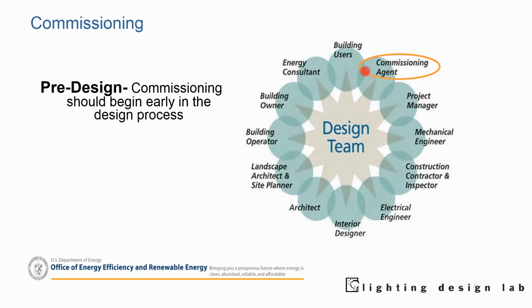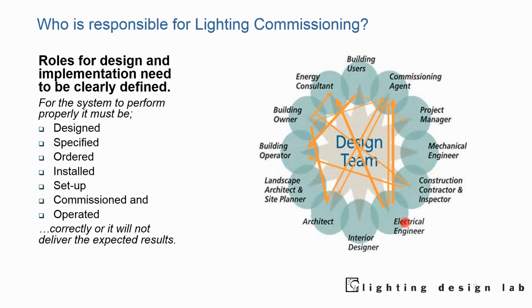Commissioning agents should be involved early on in the process. Otherwise, you can get into problems with who's responsible for what. Roles for the design and implementation need to be clearly defined and specified, and everything installed and set up and operated correctly, or it will not deliver the results expected.